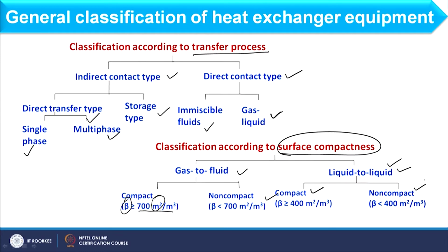Okay. Now, what is the application of these compact exchangers? Compact, as you have already understood, means that in a small volume we have to increase the heat transfer. How do we increase it? We increase the heat transfer by putting fins. Secondly, because its size is very small, its utility should be where size really matters. For example, aerospace.